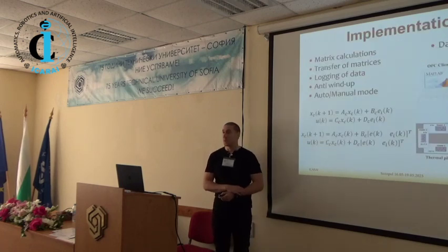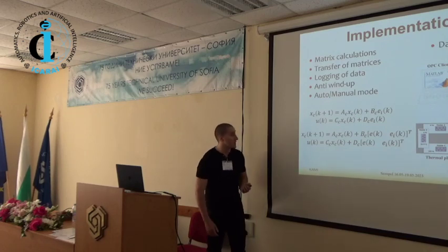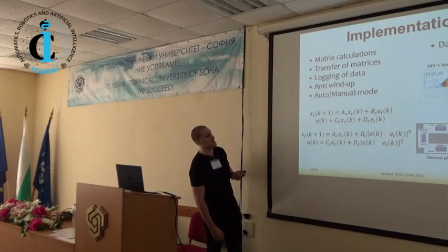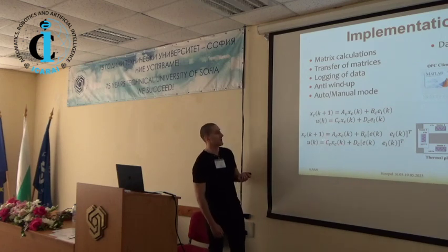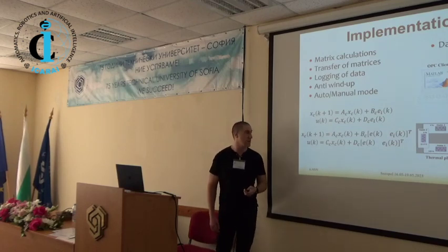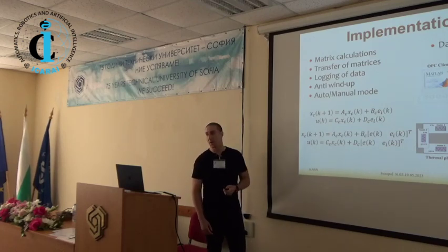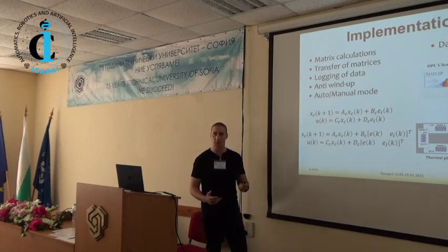Let's talk a little bit about the implementation itself. The plant is controlled with a programmable logic controller, so we need a digital implementation. The series controller is implemented in discrete state space form using these equations, where E with subscript I is the integral error. These are the equations for the parallel form. We have two inputs, the error itself and its integral. Since the parameters themselves are calculated on a separate computer, we need to transfer the matrices to the controller, and we do this by use of OPC.